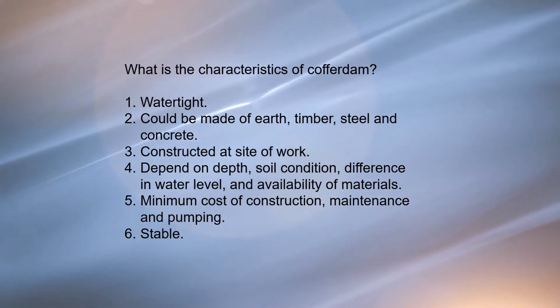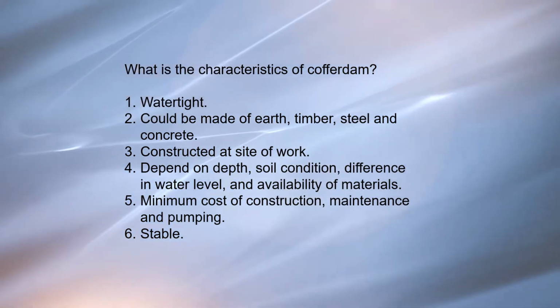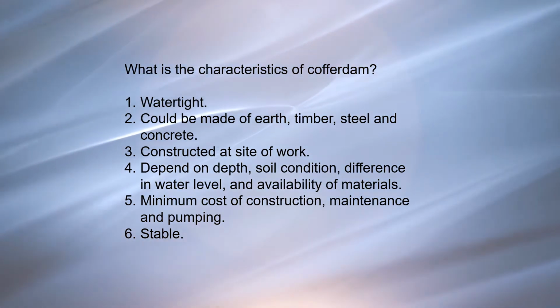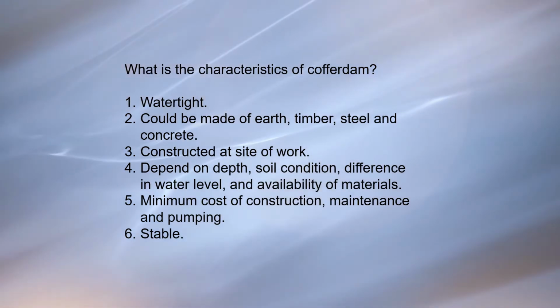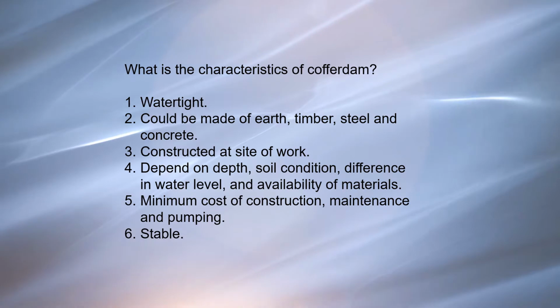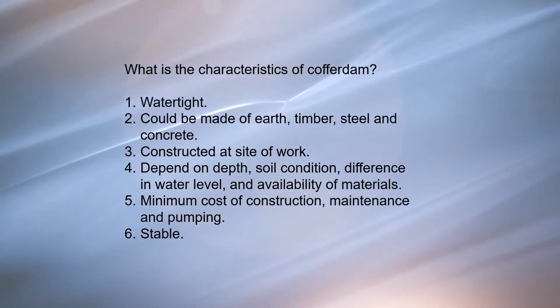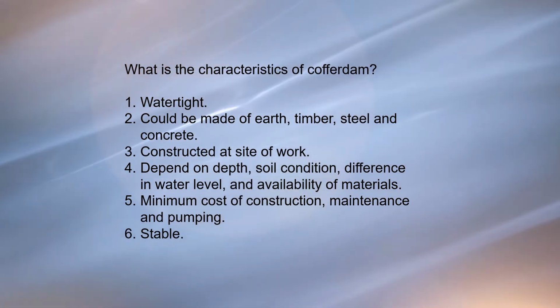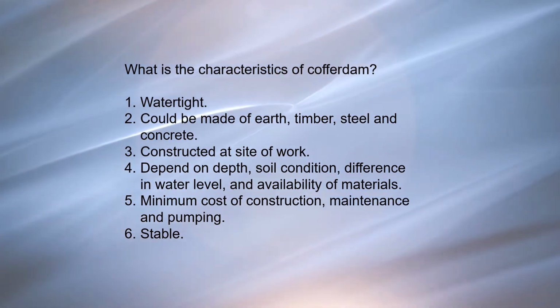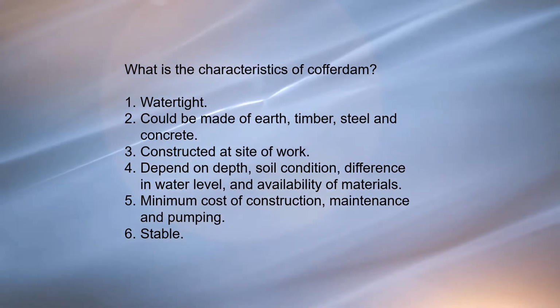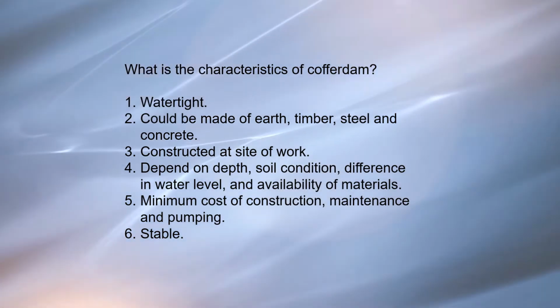Number 5, the design and layout of a cofferdam should be such that the total cost of construction, maintenance, and pumping is minimum. Number 6, a cofferdam should be stable against bursting, overturning, and sliding under the floods and waves.